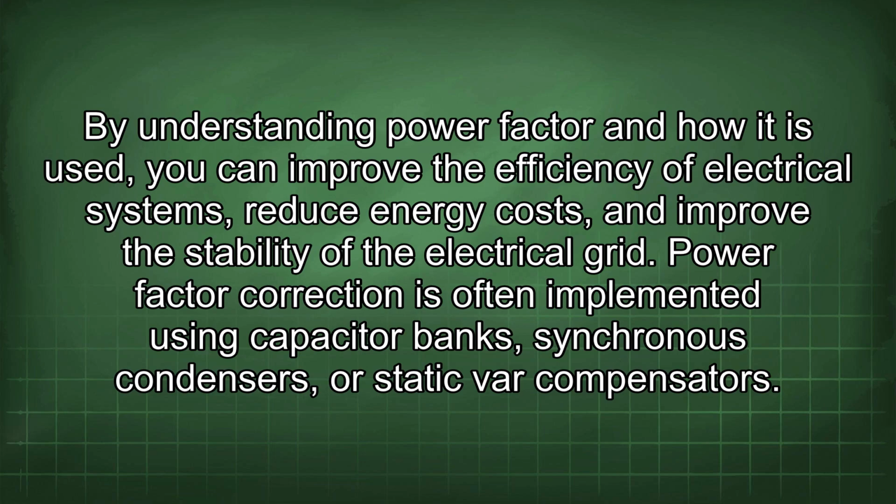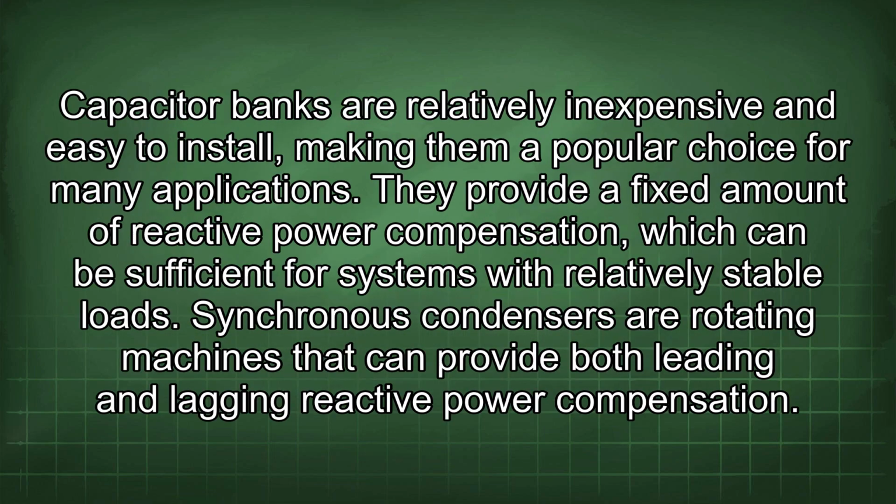Power factor correction is often implemented using capacitor banks, synchronous condensers, or static var compensators. Capacitor banks are relatively inexpensive and easy to install, making them a popular choice for many applications. They provide a fixed amount of reactive power compensation, which can be sufficient for systems with relatively stable loads.